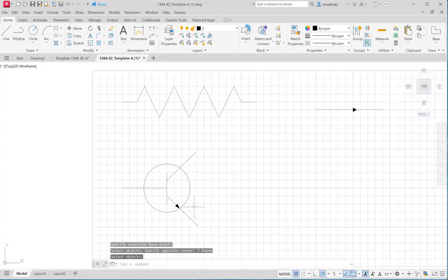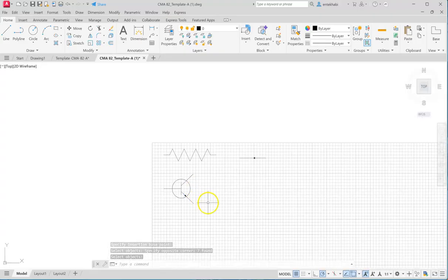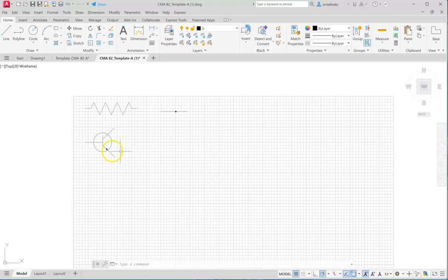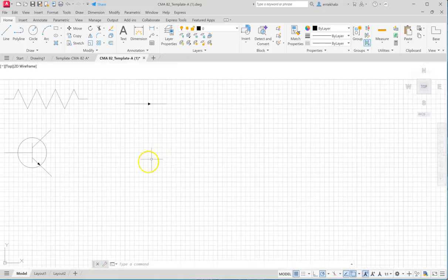Okay, next step is to insert these blocks and create your drawing. So once you've finished everything under the 0 layer, don't forget that you are doing everything on the 0 layer, finish the rest of them. And if you want me to show you, there's another one. The connection is a small circle that's easy to draw. Terminal is another circle, a little bit larger than connections. And the ground. For ground, let me show you how that can be created. Spacing between each one is 0.05. You can offset that. That offset would be a good choice on that one.